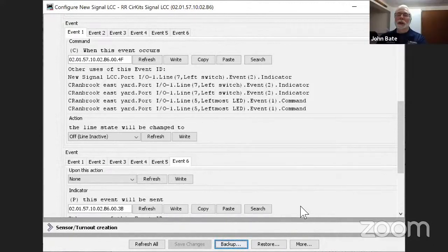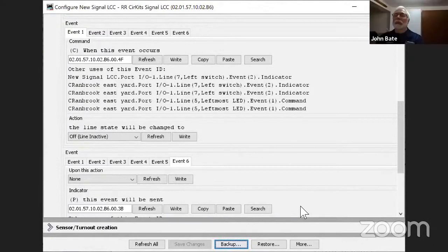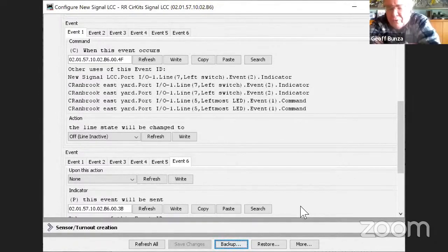It's not something for someone who's not comfortable with that sort of electronics. I can actually answer that, because I got involved in discussions with the OpenLCB group about using Arduinos, and most of the current crop of readily accessible Arduinos are underpowered for a node operation with LCC. Since that time, there are newer models that are compatible with the Arduino development that are much faster, much more capable, with much more memory. Right. So that can change, obviously.